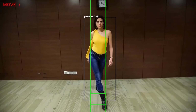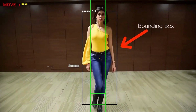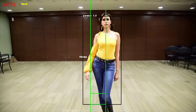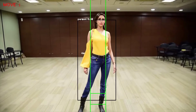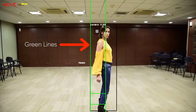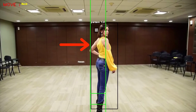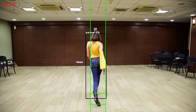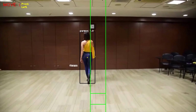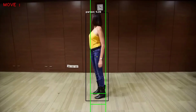This is a sample video that we have run on our software model where we can see our model can detect a woman and draw a bounding box around her, and there is a yellow dot which tells us the center of this bounding box. And we can also see that there are green lines and a green box at the center of the frame. Whenever a certain portion of the white bounding box goes out of these green lines, a move command is given to the robot in the direction so that the person comes to the center. So this is how our robot will work, and it will follow the person around.